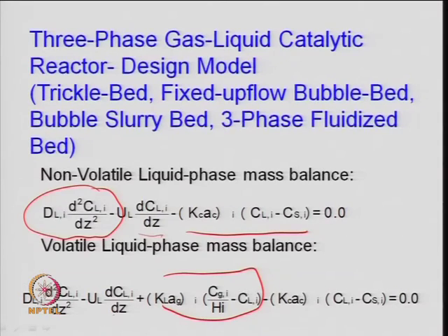Again the same term, this is again the same convective term, and this is what is reported because of the transfer of the material from liquid. So, the liquid phase mass transfer coefficient, and this is transferring into the gas, times whatever the P A minus P A I, or in terms of the concentration with Henry law, C G I minus C L, and the same thing for this term, which is common here again.